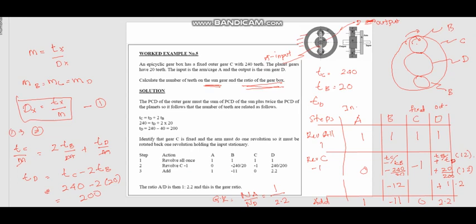So for this particular case, the one that you have to watch out for is this. You have to remember this. Right? So basically, as B rotates, it will mesh with D. So the TB over TC actually defines one rotation of B per rotation of D. So how much D will rotate based on one rotation of B. But again, as mentioned just now, B does not rotate once, but it rotates 12 times. So that's why you have 2 times 12. Okay.